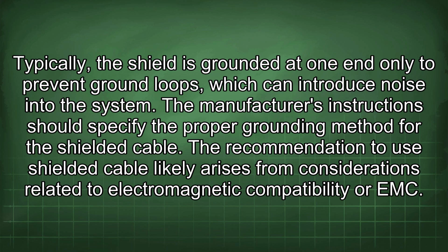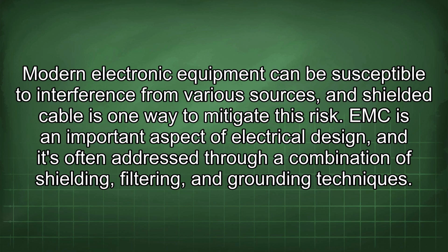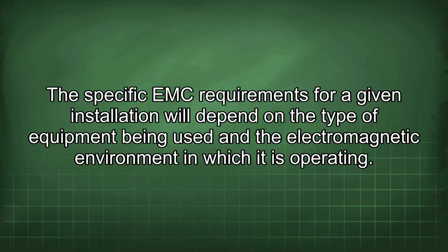The recommendation to use shielded cable likely arises from considerations related to electromagnetic compatibility, or EMC. Modern electronic equipment can be susceptible to interference from various sources, and shielded cable is one way to mitigate this risk. EMC is an important aspect of electrical design, and it's often addressed through a combination of shielding, filtering, and grounding techniques. The specific EMC requirements for a given installation will depend on the type of equipment being used and the electromagnetic environment in which it is operating.